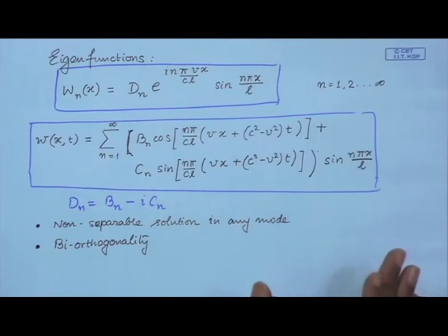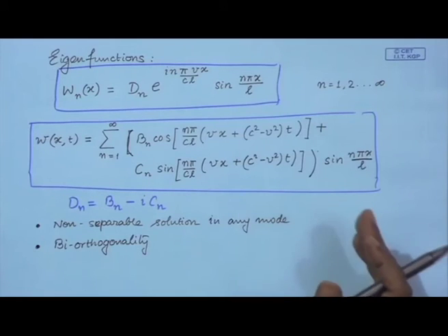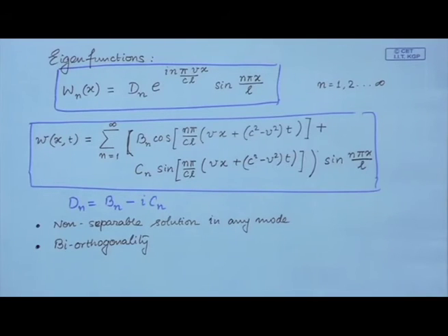Now, we have been using this modal analysis or the modal solution for solving initial value problems, forced vibration problems, damped vibration problems, etc. And in every one of these problems we had to use this orthogonality to solve the system. Since this orthogonality is now non-trivial, it becomes a little cumbersome to use the modal approach for solving various problems for travelling strings, but there is a convenient approach which is using the Laplace transform technique.